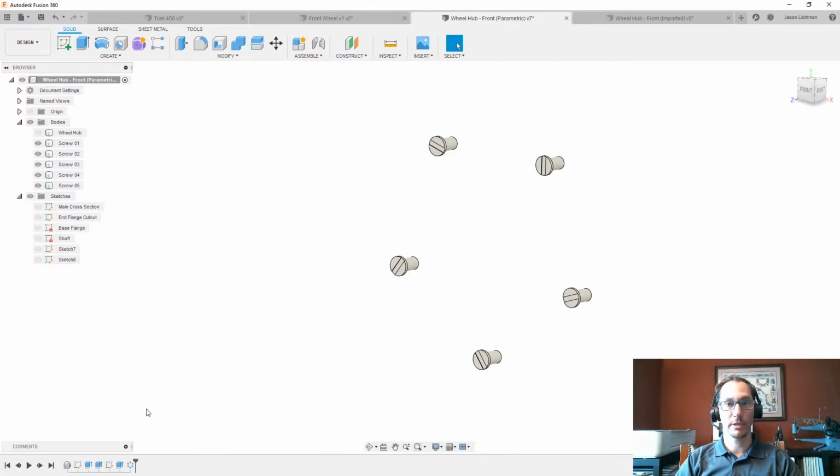Now, some of you have probably already figured out that there are certain things that you just cannot do when the history is turned on. I'll tell you why that is, and then give you a couple of examples of things that you can only do with the history turned off. The reason is that they're incompatible with the methodology of how parametric modeling works. They don't work together. If you turn the history off, now you're in this direct modeling environment and you can do some things that you couldn't do otherwise. So let's give you an example.